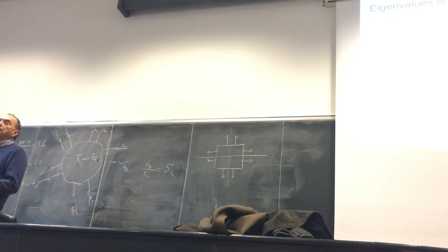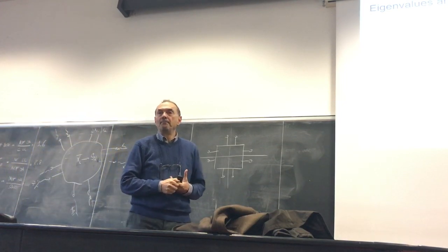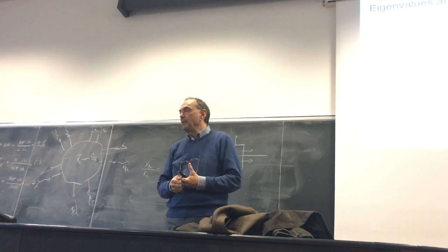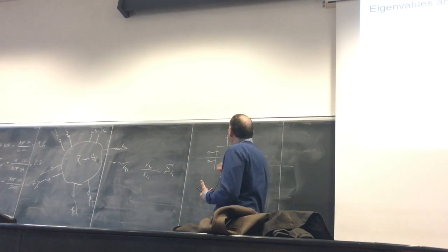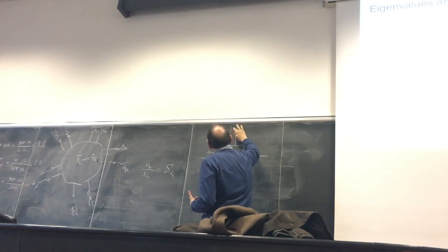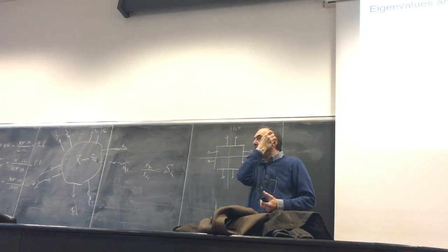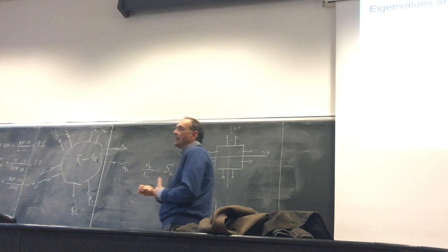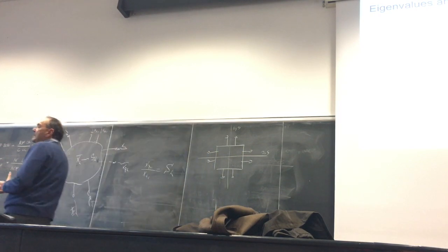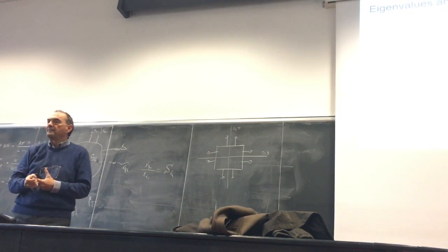And with these two symmetry planes, I will have 4 possible combinations of electric and magnetic boundary conditions. In other words, I can set each plane open or short. In correspondence to each of these conditions, I know what the eigenvector I have to use is.